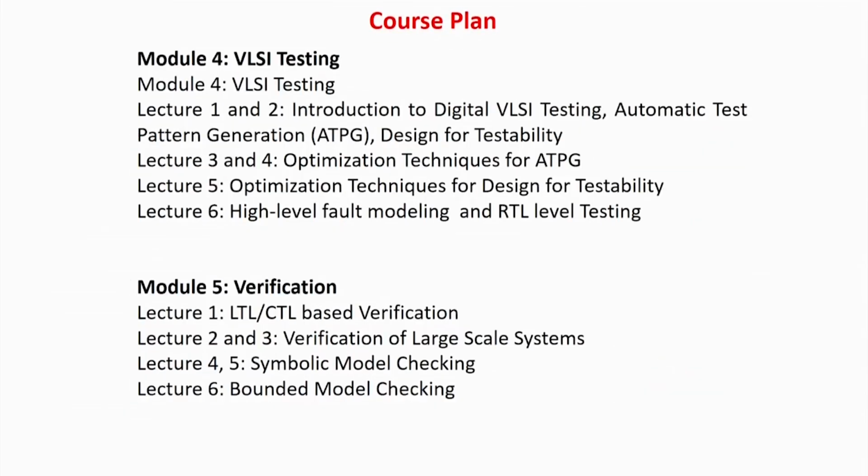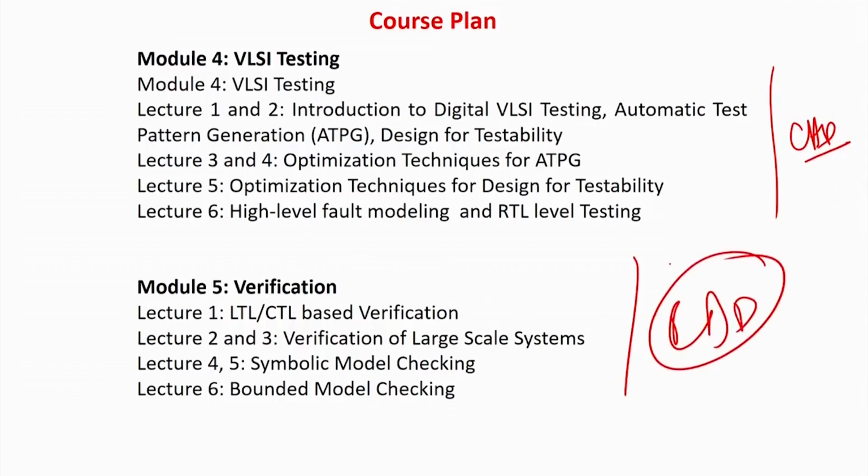Then there will be an entire module on testing. So given a circuit, how can you generate optimal test patterns in a very fast way? This is also more or less fully done by CAD tools. Verification is also mainly done by CAD tools. Just the model you have to write, the FSM you have to design, and the specification to be tested. After that it is a model checker which will tell whether the specification is met or not.